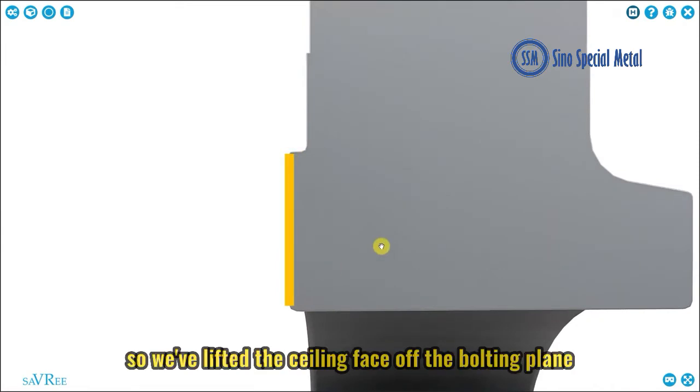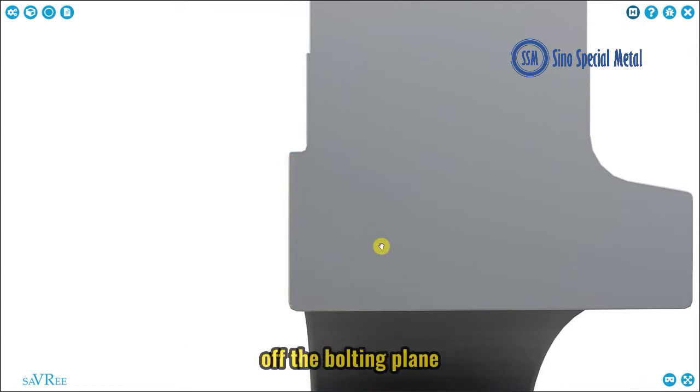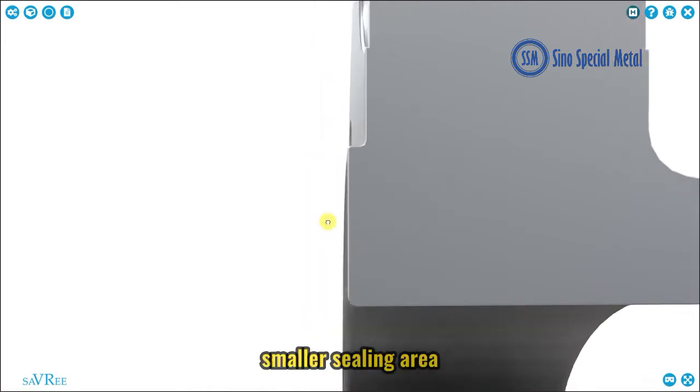So we've lifted the sealing face off the bolting plane. The amount we actually lift the face off the bolting plane depends upon the pressure that the system will operate at. But let's forget about that for now. The big difference then between a raised face and a flat-faced flange is that the raised face is raised off the bolting plane and we have a much smaller sealing area.